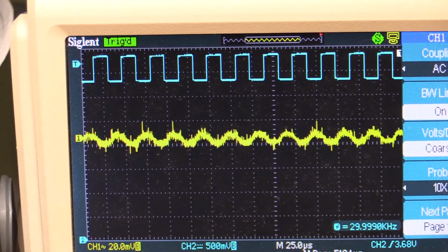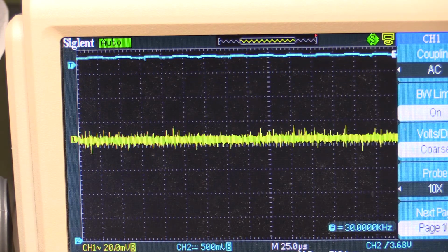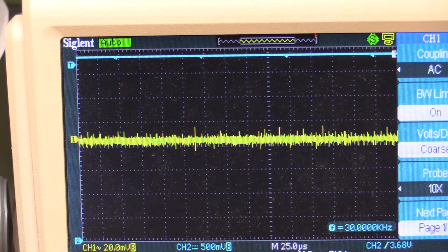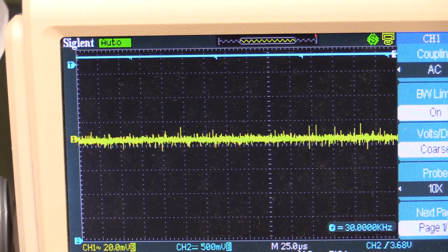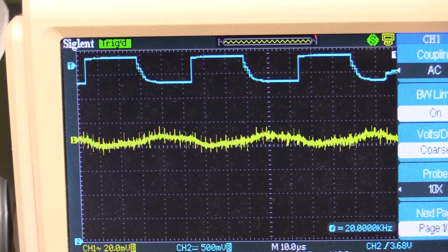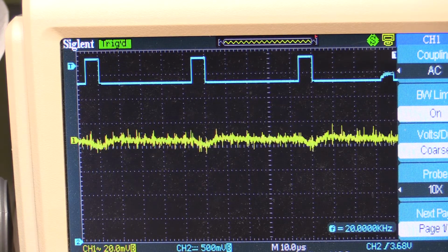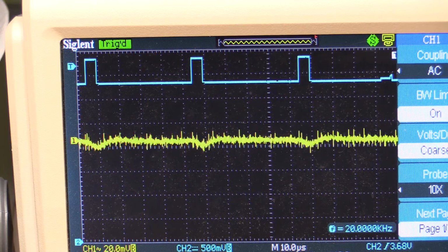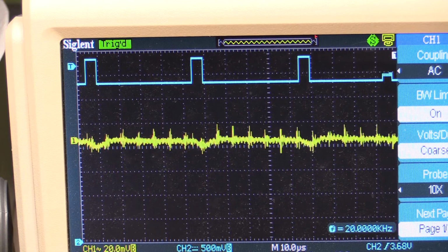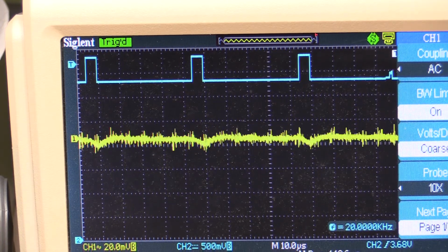If I take this back to maybe a pulse waveform, just to try and see if I can make it. So that's a 33 microsecond pulse. Let me just adjust the pulse width, just trying to make sure I can see the transient response. So that's a 5 microsecond pulse of 2 amps. So I'm swinging it from 1 amp to 3 amps output for 5 microseconds.